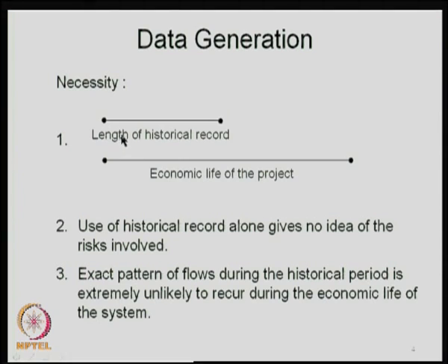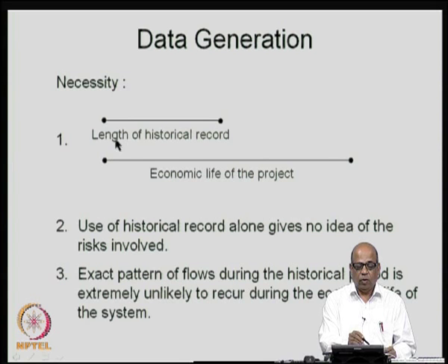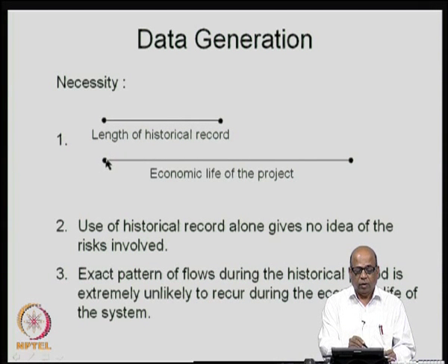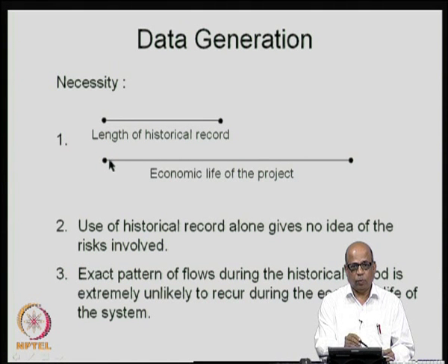Why is it necessary? Like I said, you have let us say a length of historical record. Let us say this is about 30 years, and you would like to use this 30 years of data at a particular location for, let us say you want to develop a reservoir project there. That means, you want to build a dam and then construct a reservoir there. The economic life of the project itself may be of the order of 100 years or 150 years. So, you are going to make a decision for the next about 100 years based on the last 30 years of data.